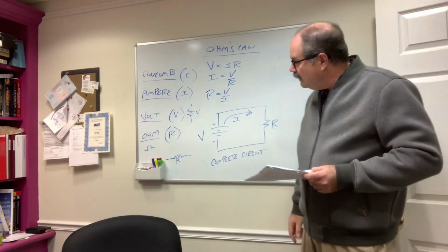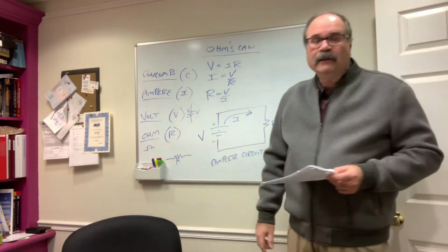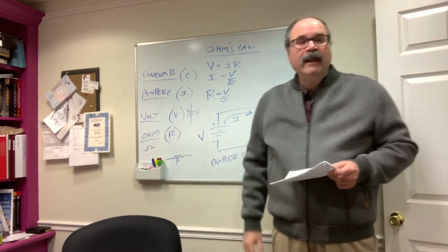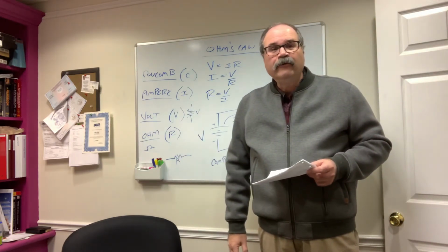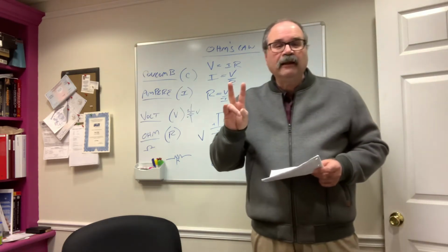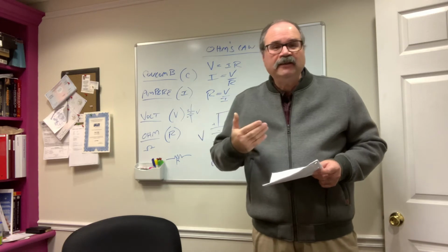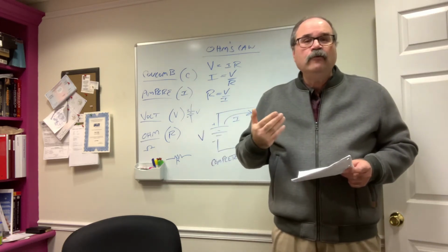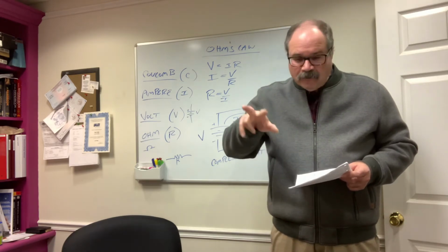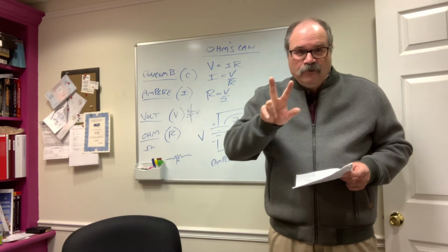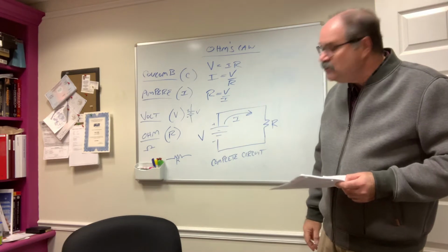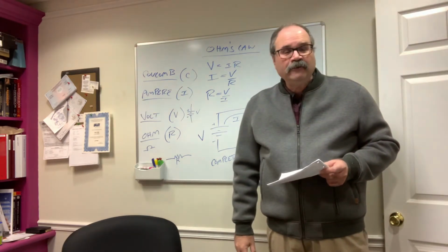Voltage in a DC electrical circuit represented by the capital letter V. I've also listed here the schematic symbol for a battery that has positive and negative polarity. So the formal definition of voltage is the difference of potential between 2 points in an electrical circuit. And as you're going to see, this is going to become very practical. When you measure voltage in lab with your digital multimeter, your 2 test probes, you're always going to measure voltage in 2 separate locations.